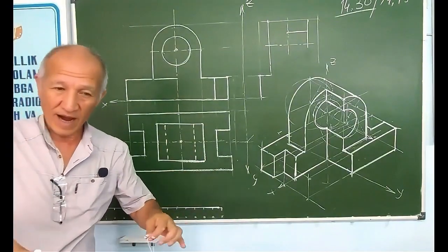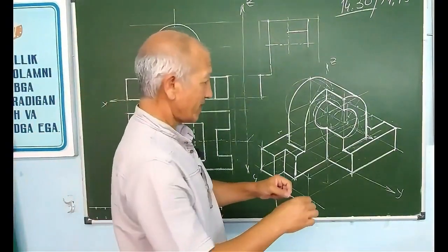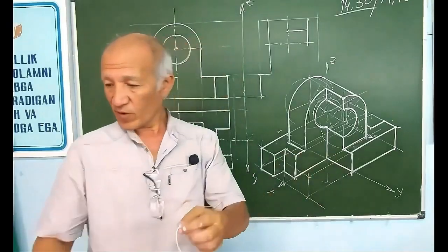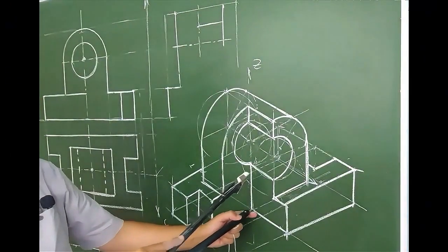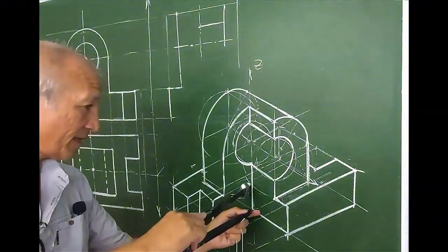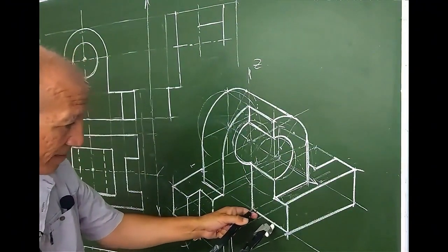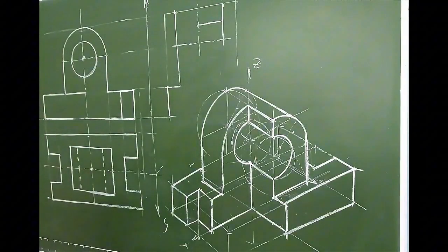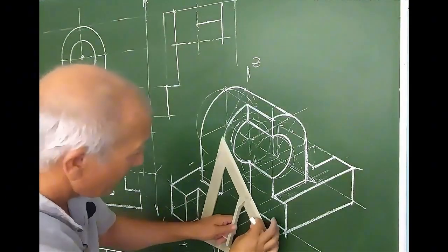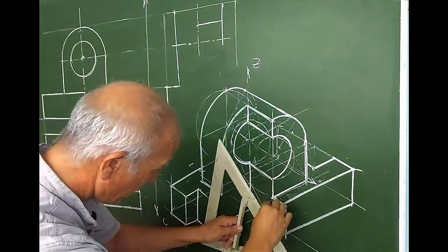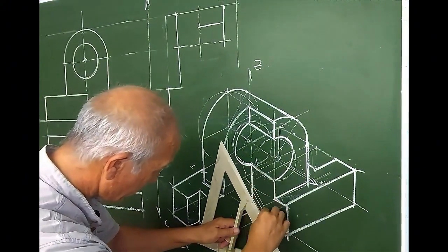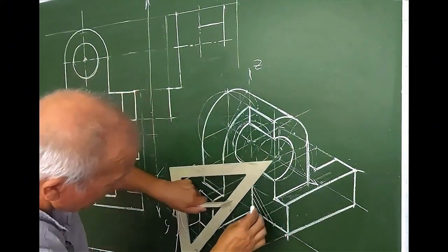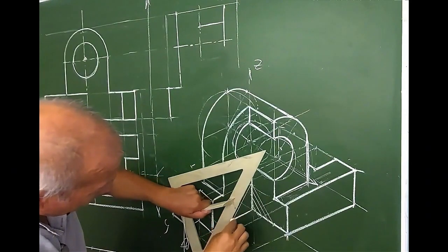Now about the matter of hatching, as I said last night as well, 60 or 70 times. Take any compass you want. Here you are working with a compass. Place it here, take the same distance, and put a point here. Put a point here. Put a point on this side. Can you manage that? Once you have carefully placed it in the correct position, you can begin to hatch it. Now, can you hatch it exactly like this, making sure that it stays perfectly parallel just like this? There you go. That is looking much better now.